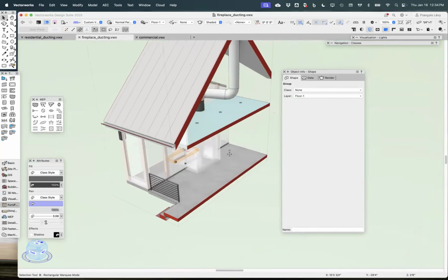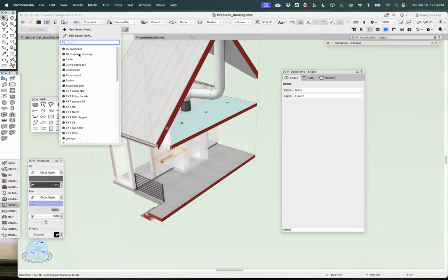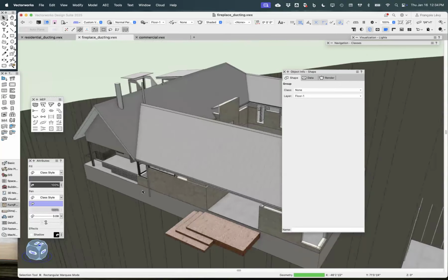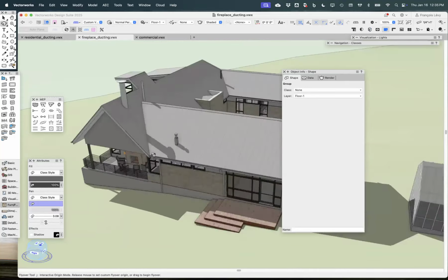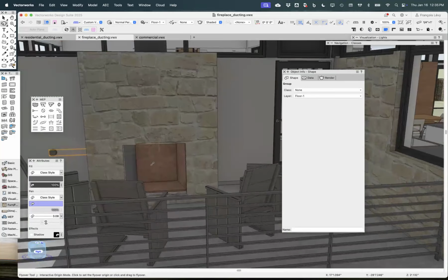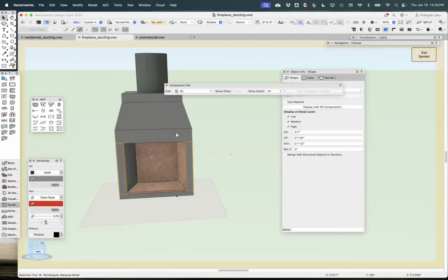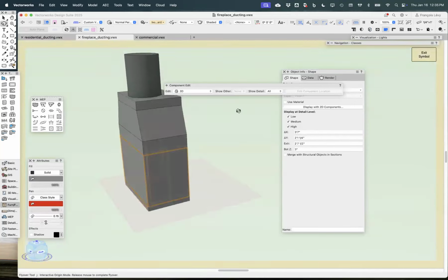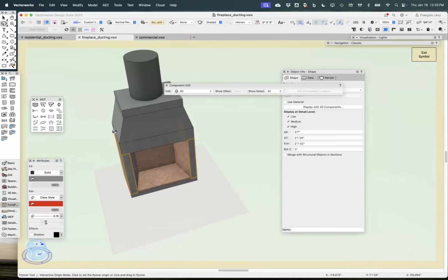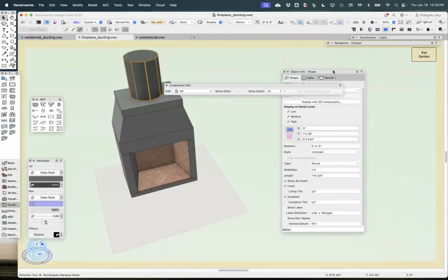And that's that. And then in this case, I'll just mention it since we were also talking about fireplaces. In this case, I didn't build the fireplace with the fireplace tool. This is an Isokern, and those have very specific dimensions. And so we sort of built a symbol of an Isokern fireplace and just kind of stacked it all up. And that's also the flue, the 20-inch flue is just another short piece of duct that we know we have to tie into. So you can mix and match.